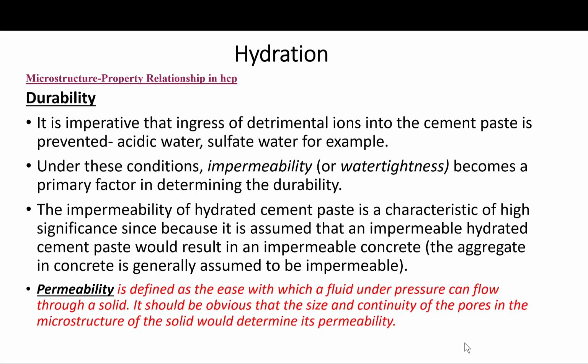Let's talk now about durability and how it's impacted. The hydrated cement paste is alkaline, as we mentioned, so exposure to acidic waters is detrimental to the material. Under these conditions, impermeability or water tightness becomes a primary factor in determining the durability.